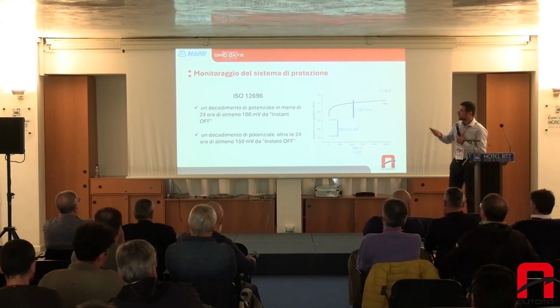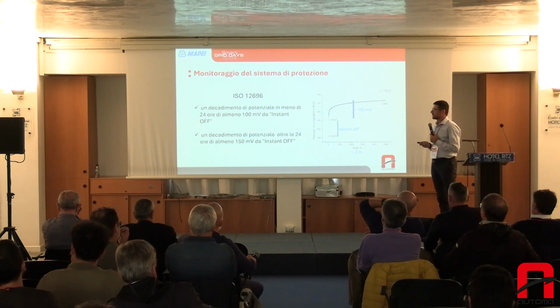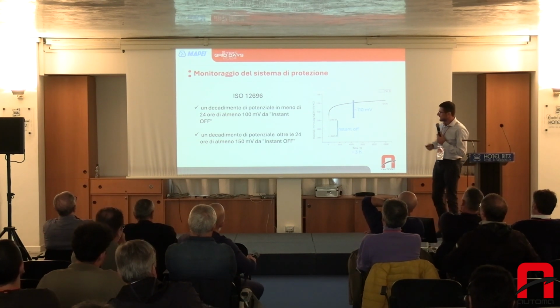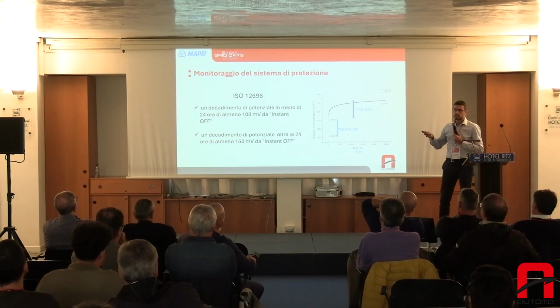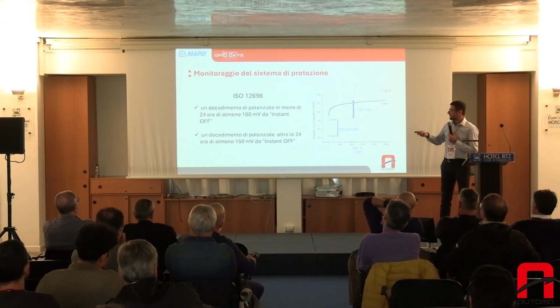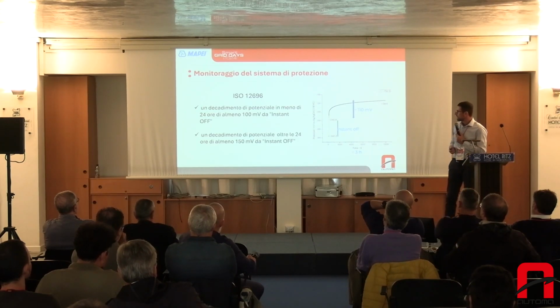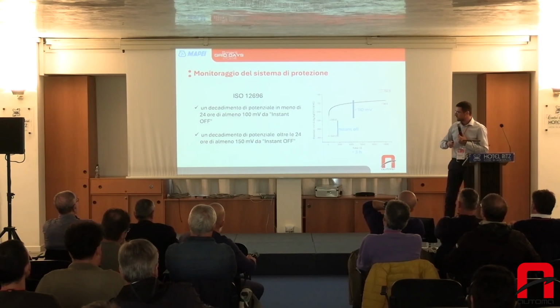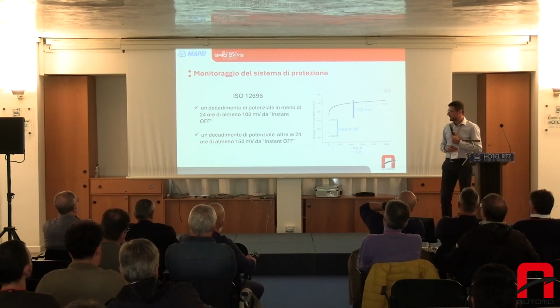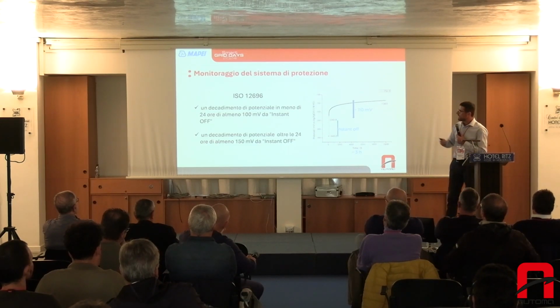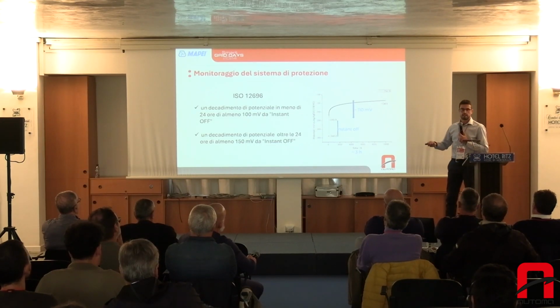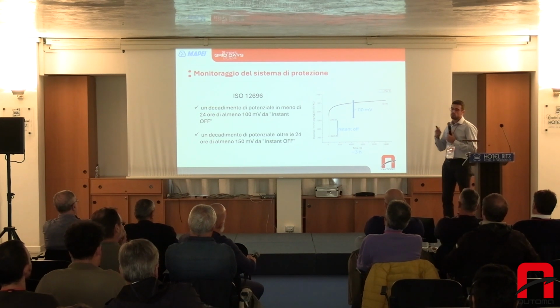As I already mentioned, the system can be monitored according to the ISO 12696 standard. There are two possibilities for measuring. You assess the potential drop, taking out the instant off value. This is a measurement that was done a few years ago in Spain. And here you can see that in a few hours, 3 hours, you are able to reach the value that the standard requires.